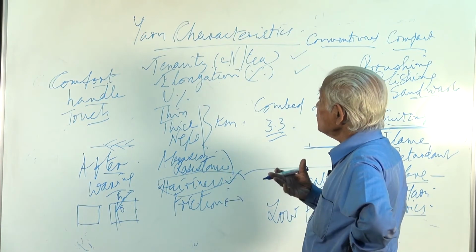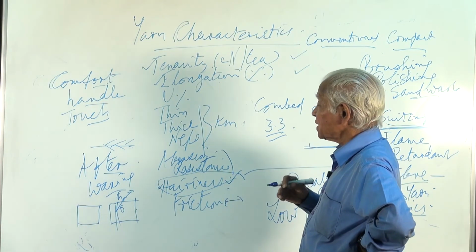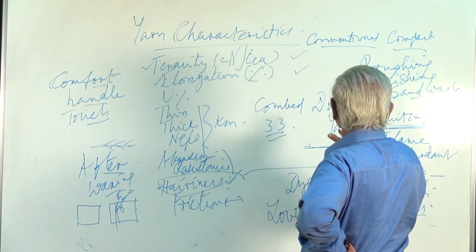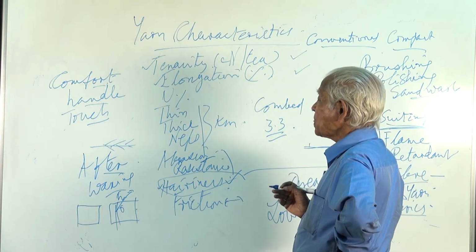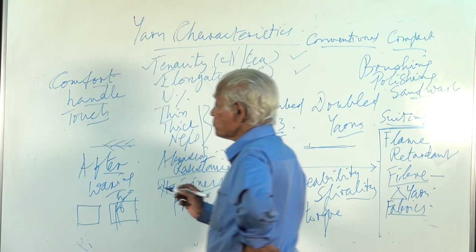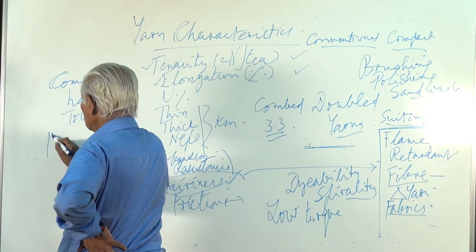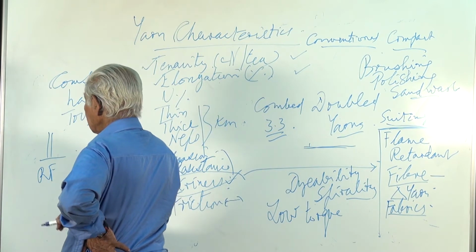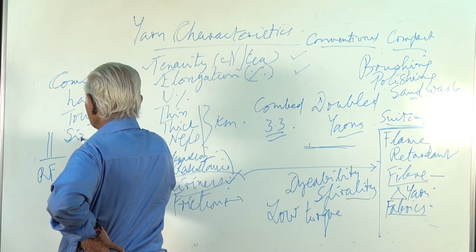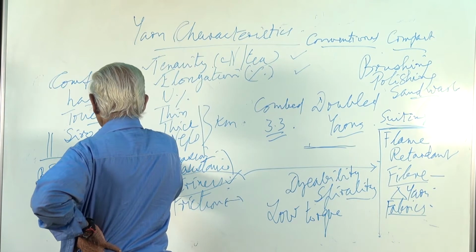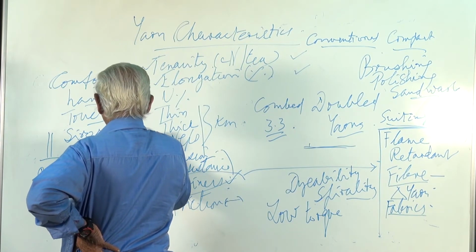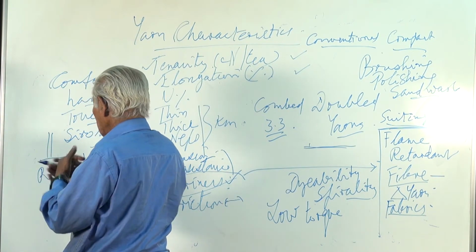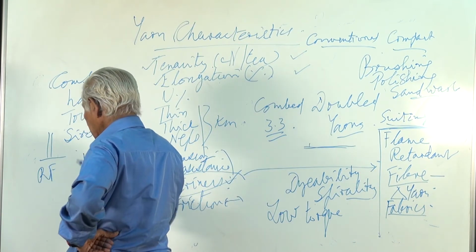So we have found that most of the improvements that have been made in spinning, particularly the compaction, and even in the compaction, it is possible to produce a two-fold yarn in the ring frame, so that production of a double yarn is avoided. Earlier, this was called gyro spinning, feeding two rovings in the ring frame and getting them drafted separately and then combining them to produce a so-called doubled yarn.